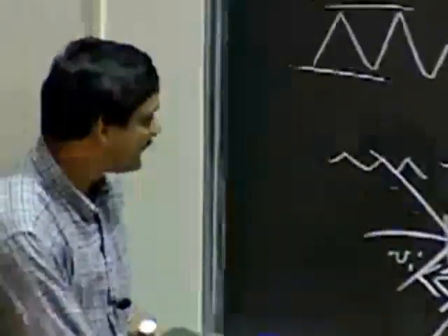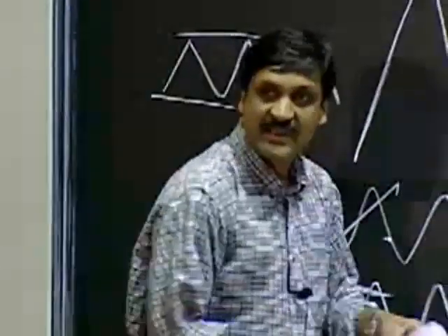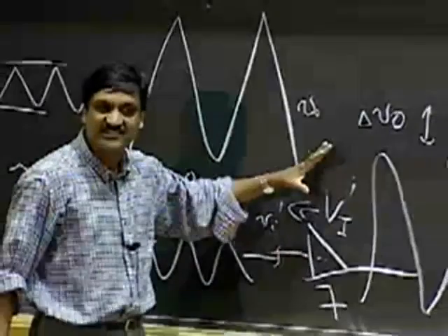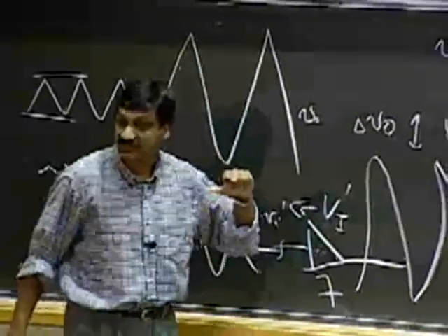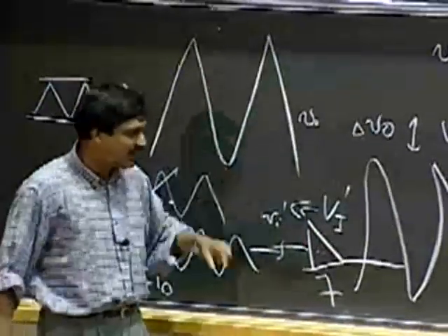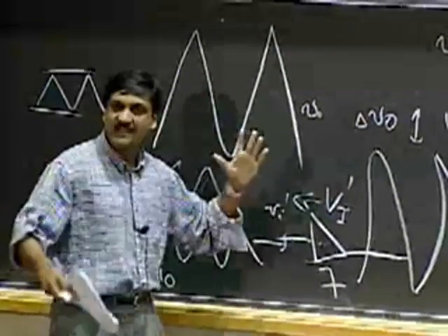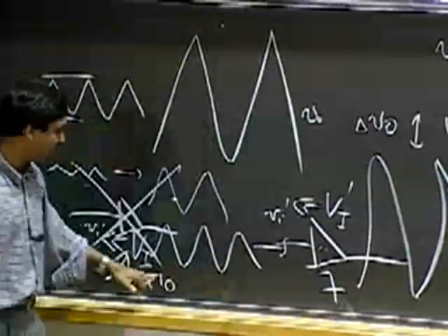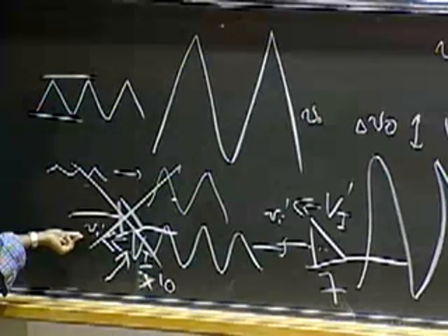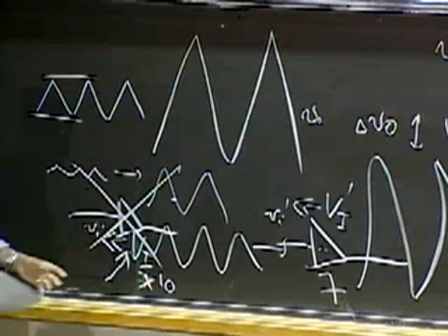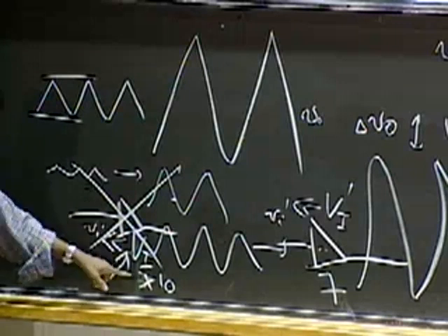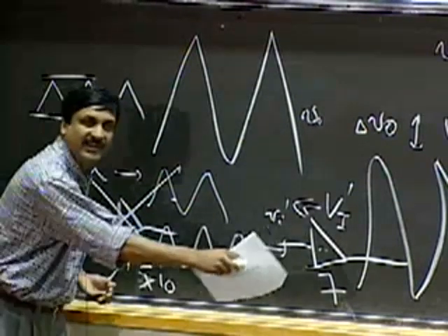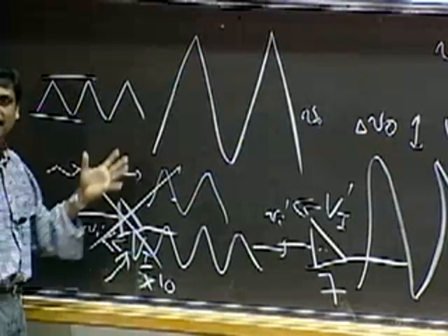It turns out that when you design your amplifier, in order to meet the saturation discipline and so on, you have to choose values of RL and VS and stuff like that, and be within power constraints. So the amplifier doesn't blow up. And by the end of it all, you're going to get a measly 7x gain out of it. Same way here, to deal with a very small signal and get some amplification, another set of values, and you get 10x. So they multiply. It's much harder to build one amplifier with a much larger gain.